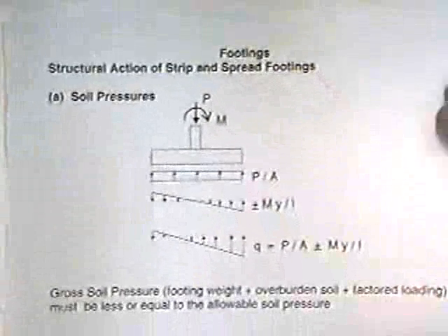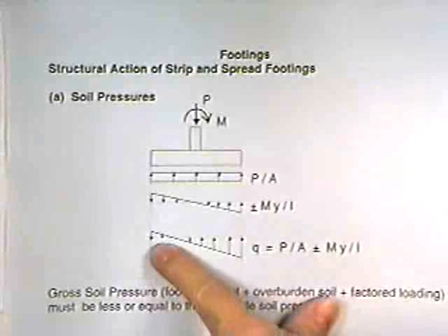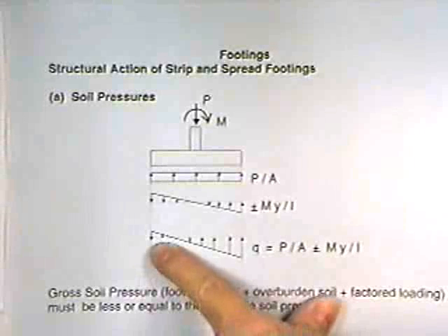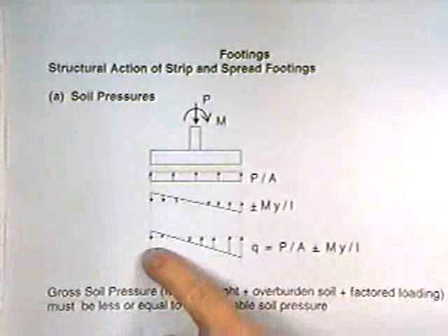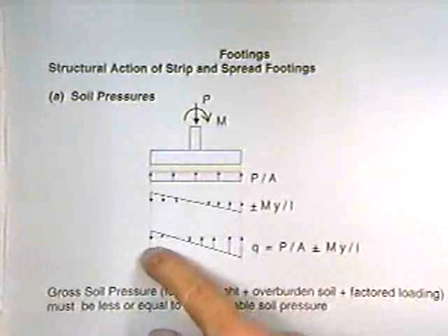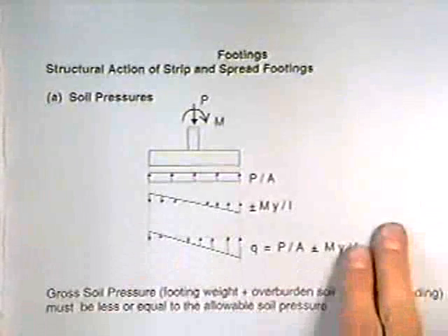You might mention, too, that if the stress distribution ever really looked like that in soil, they're probably going to ask you, is it acceptable? Soil can't come up with any tensile stress. Right. So if the side really ever did come up with a tension stress, that wouldn't be acceptable because this little piece can't be developed. Did everybody catch that?